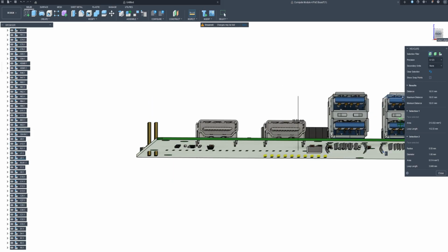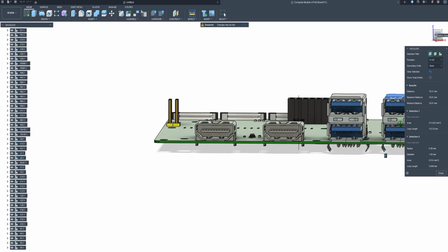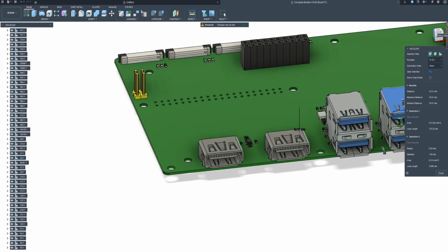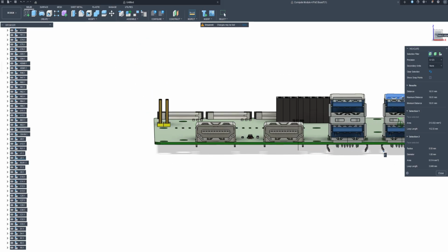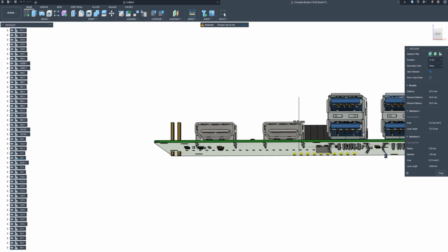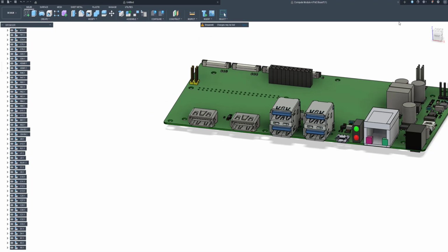So that's the minimum, because that's the farthest point. So we know the depth we're working with, the minimum depth. So we're going to make sure that the case itself has a minimum depth of 20 millimeters. And we're going to be creating our custom standoff and everything. But first we're going to be working on the backplate.